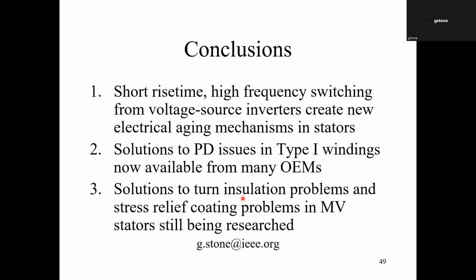I think it's time to come to the conclusion and basically say, hey, if you have short rise time, high voltage switching impulses from PWM voltage source inverters, it will create some new aging mechanisms for stator windings and rotor windings if it's a doubly fed induction generator, more than the normal aging mechanisms that would always occur anyway, the normal thermal, thermomechanical and mechanical and contamination related aging failure processes.